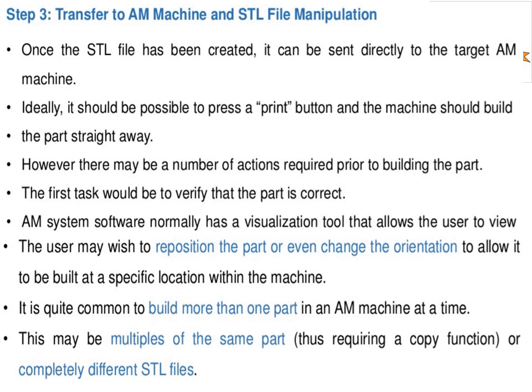Conceptualization and CAD, conversion to STL, transfer and manipulation of STL file on additive manufacturing machine, machine setup, building, part removal and cleanup process, post processing of the part, and application.